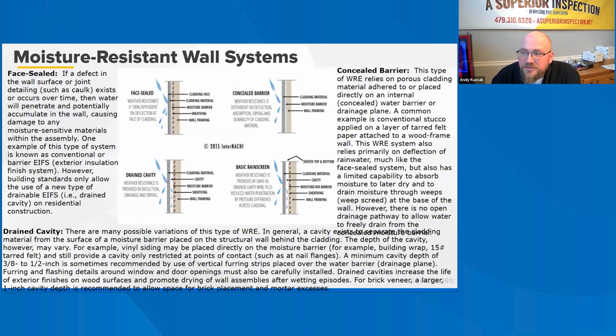In addition, the use of roof overhangs provides performance benefits for all cladding systems by reducing the moisture load experienced over time and by allowing greater opportunities for the walls to dry in the event of a periodic wetting due to wind-driven rain. The life expectancy of various siding materials may vary widely, from 10 to as long as 100 years or more, depending on the type of material, climate exposure, maintenance, and other factors.